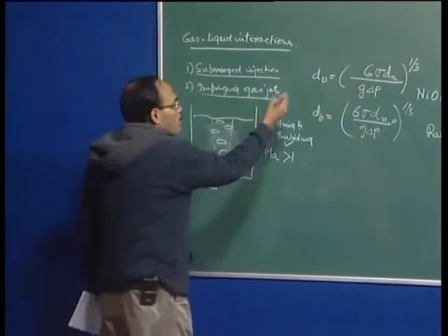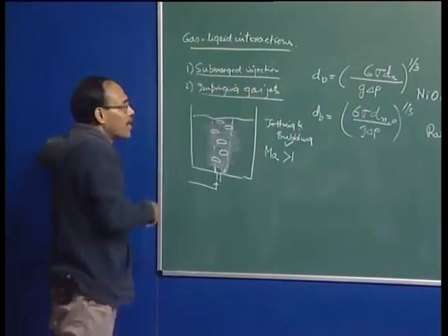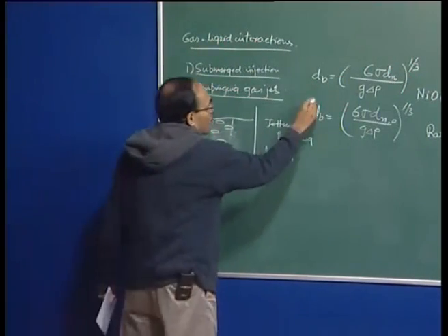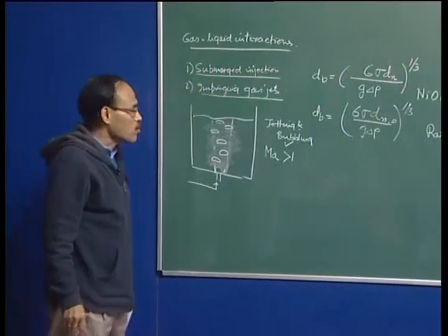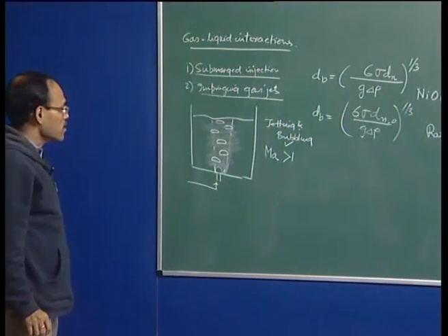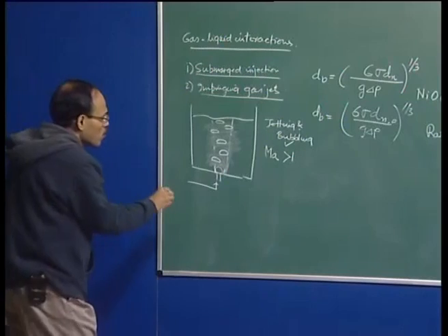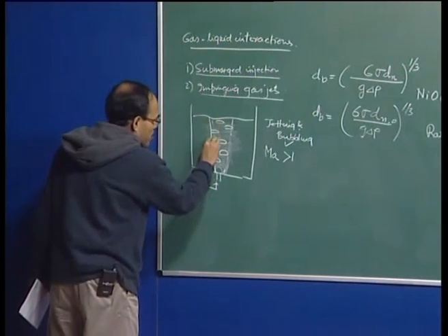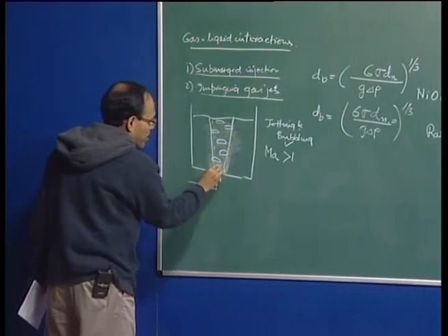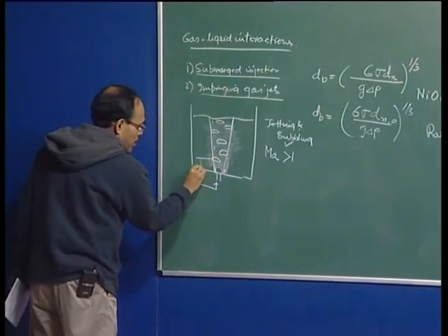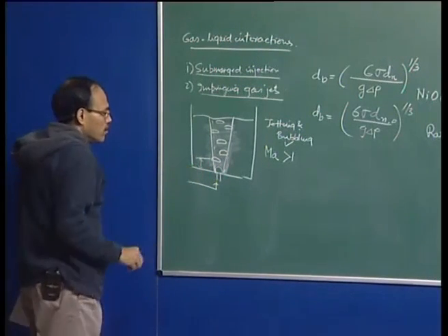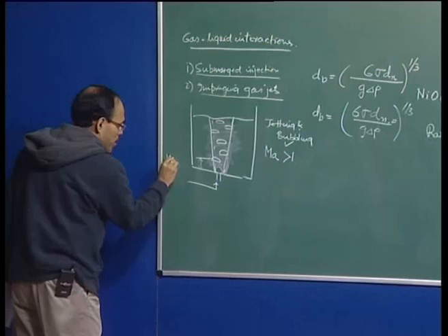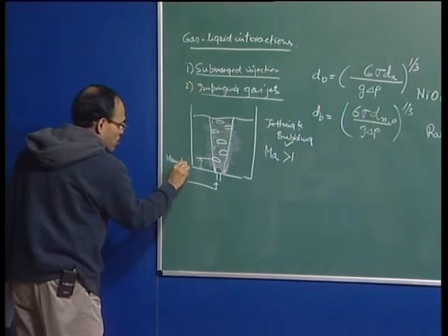So, the small bubbles forming at the orifices are going to be calculated, but these are single bubbles forming at the orifices. Very rarely are such conditions encountered in the system. Now, when we have bubbles, we basically have 4 different regimes. We have a plume here, and we can say the first regime is the momentum region, where the momentum of the jet gas is dominant.